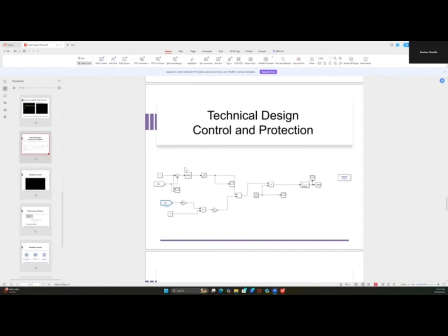from stress. If the current continues to rise and triggers comparator 2, a shutdown latch is activated, forcing the pulse width modulation signal to 0 and isolating the converter. The latch can only be cleared through manual reset, ensuring the fault is verified before restarting. Together, the clamp down and shutdown mechanisms form a two-stage protection hierarchy that preserves the converter stability and prevents catastrophic failure during fault or overload events.